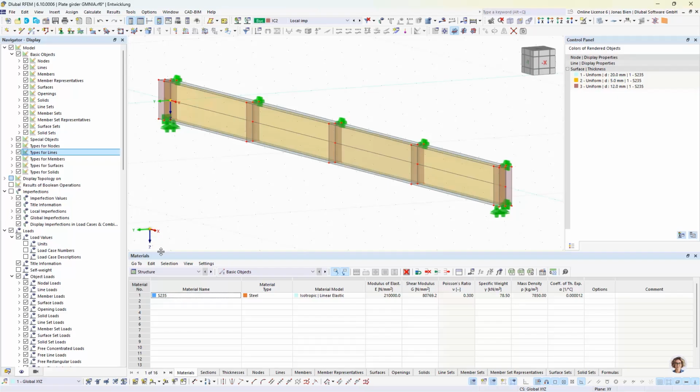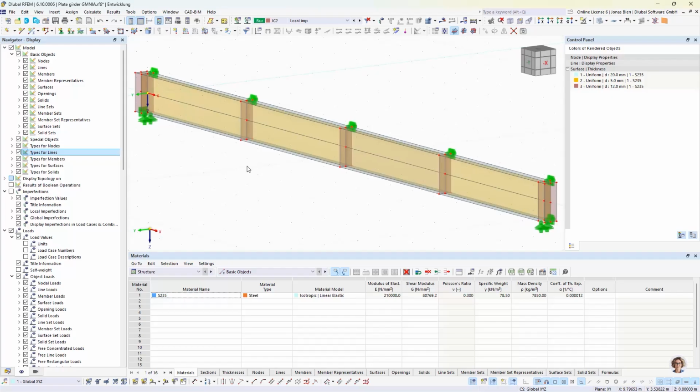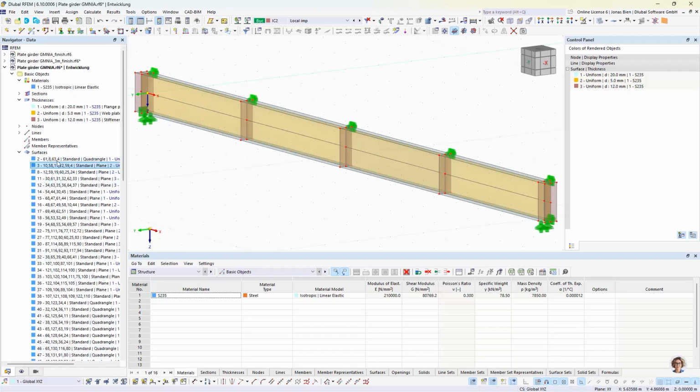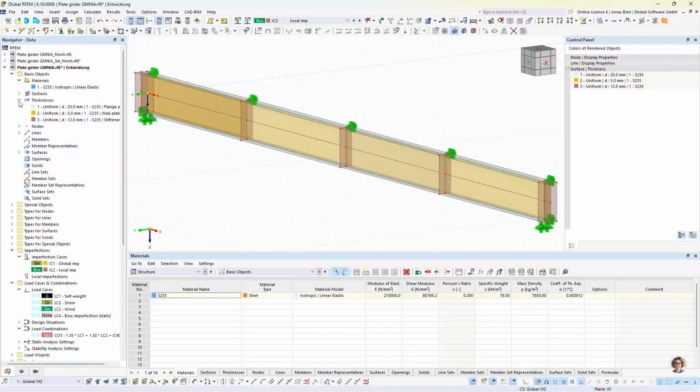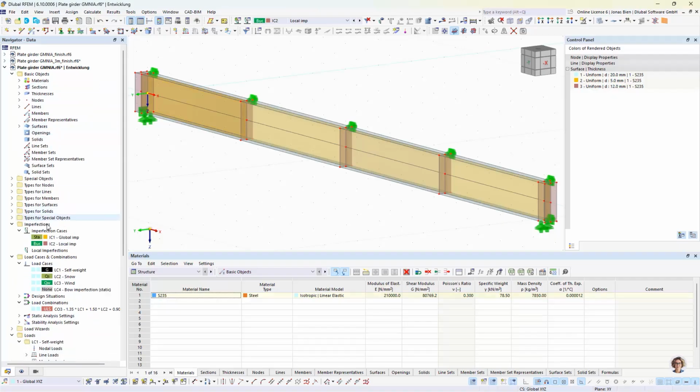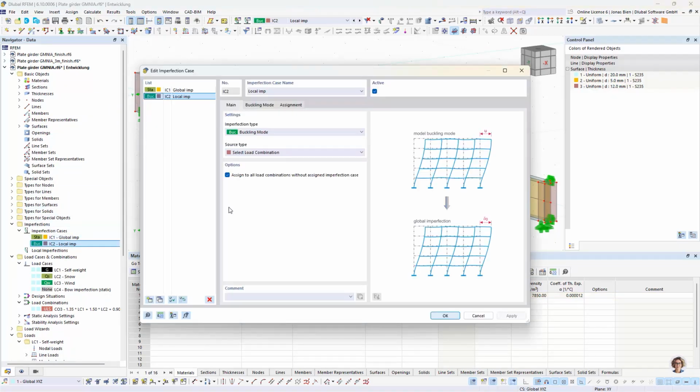So we could either put in a lot of effort to select the most critical one and apply 100% amplitude magnitude to this, or we can just, on the safe side, assume the full 100% for all imperfections, and the ones that do not really harm our simulation will just more or less do nothing. Of course, we could refine it later if we want, or if we find that our solution is not economic, but due to time limitations, I don't want to do that here.